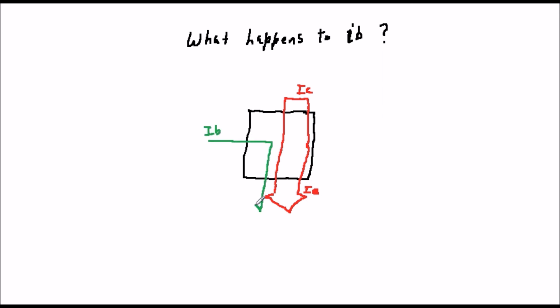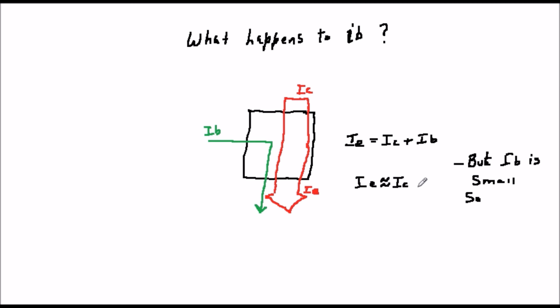It should, however, be noted that in large power transistors, beta is much smaller, typically in the range of 5 to 100. The operation of a transistor which we've just discussed is its use as an amplifier. However, it should also be noted that it is used sometimes as a switch, and the switch mode is distinct from the amplifier one. We'll discuss the switching application of transistors a little bit later in the course.